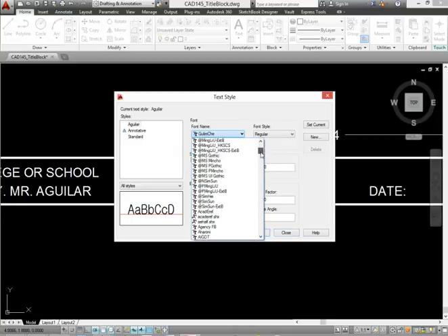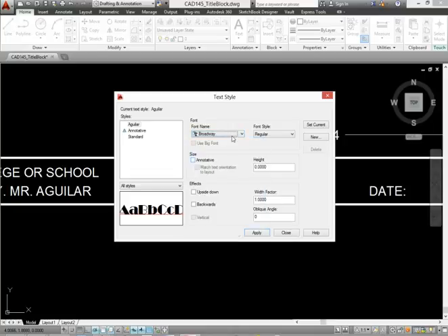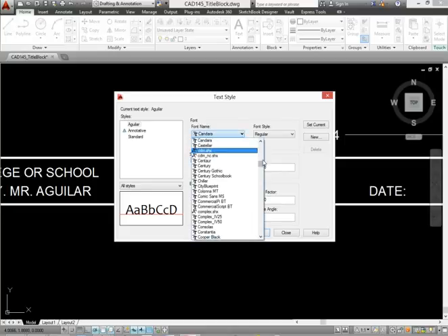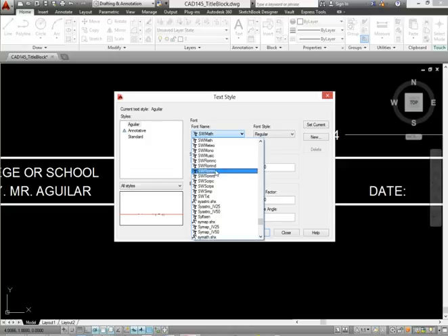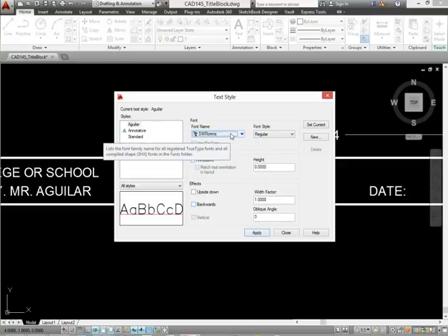There's some common rules you need to follow with textiles. You need to choose a font that does not have a serif. That's too artistic. That is sans serif, they call it. So that'd be a good choice. That is sans serif, but it looks too artistic. A very common style for drafting text is SW Romans. That's more appropriate. So choose something.